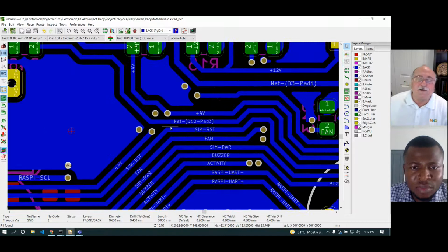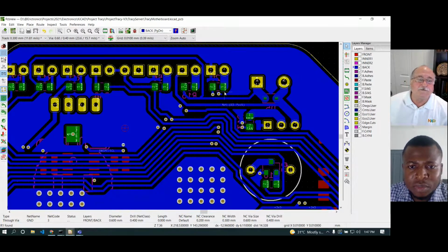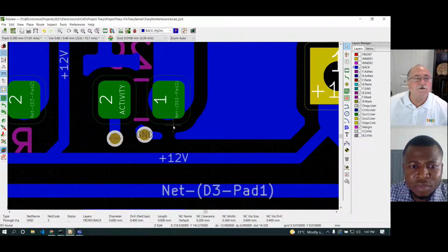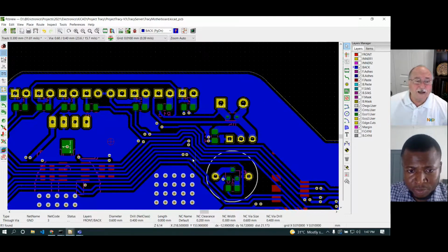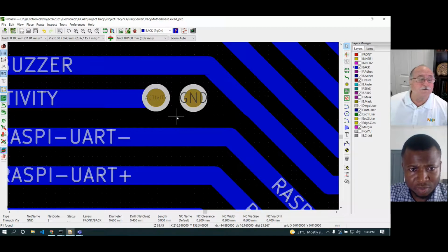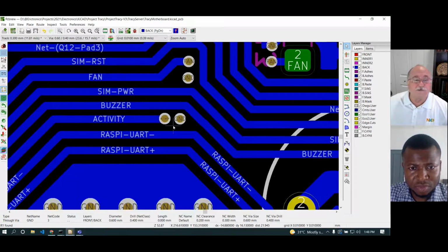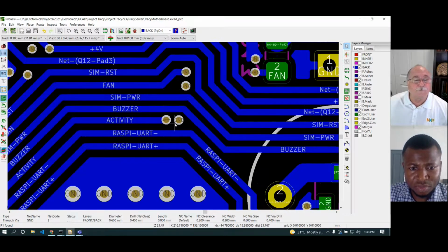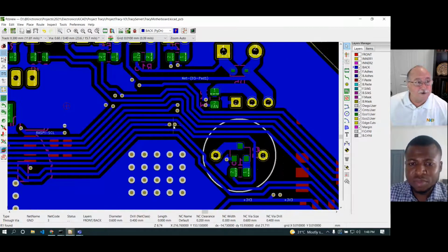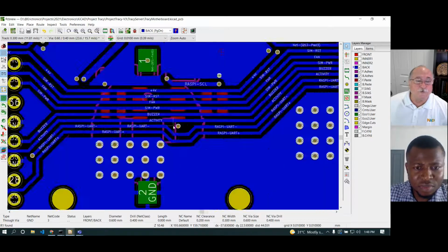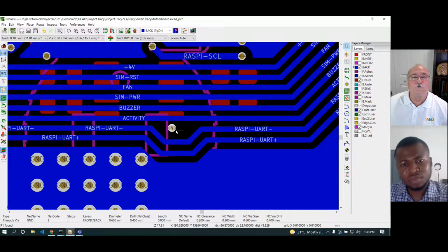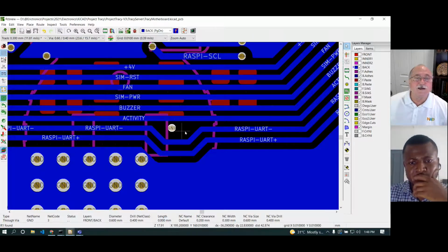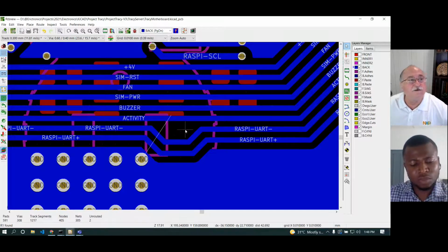If you don't put a ground via there, the energy will find the nearest one. It will spread out through the board stack and interfere with other signals around it as it tries to get from the space between 4 and 3 up to the space between 1 and 2 or 2 and 3, or back down again. So what we want to do is go through, and I start on 4 because that's where you can see orphan vias.